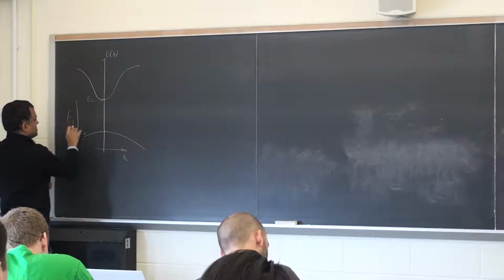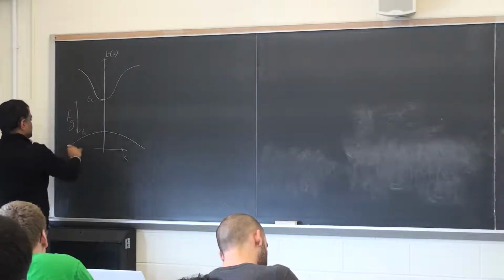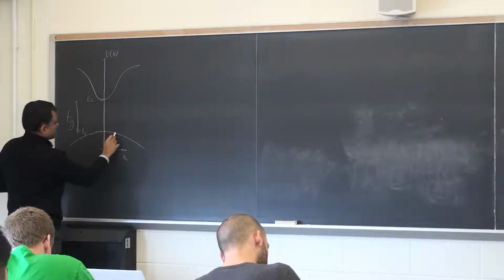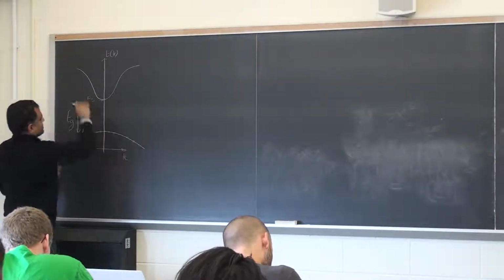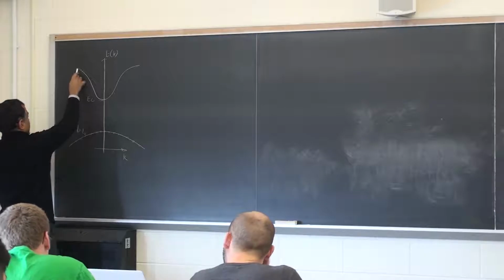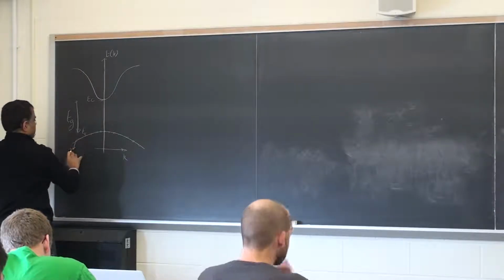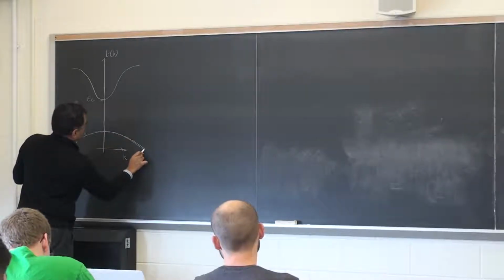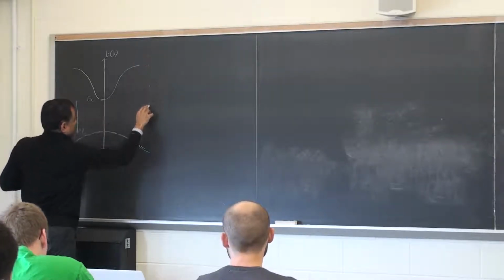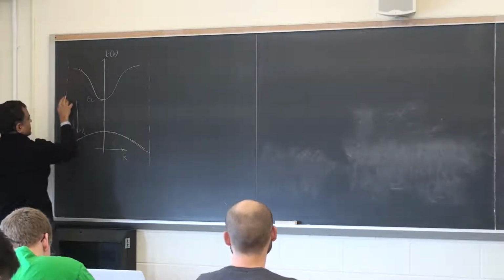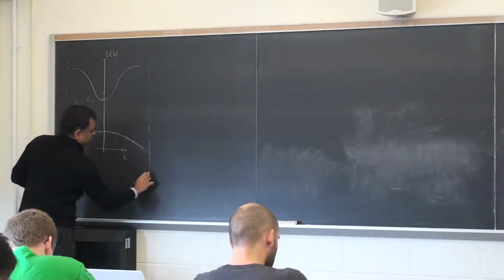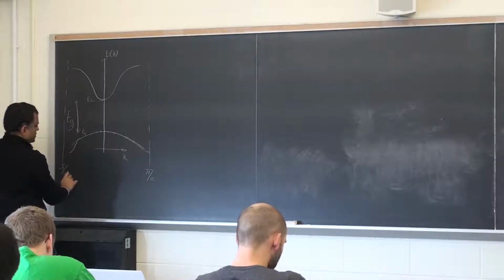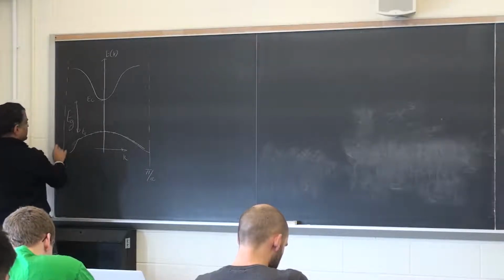E sub g. Right? And the states here are completely filled with electrons in a semiconductor, and the states there are empty. And just to be a little more complete, the curvatures here go around, and this periodically repeats with pi over a to minus pi over a, which are the reciprocal lattice vectors in the k space, right?